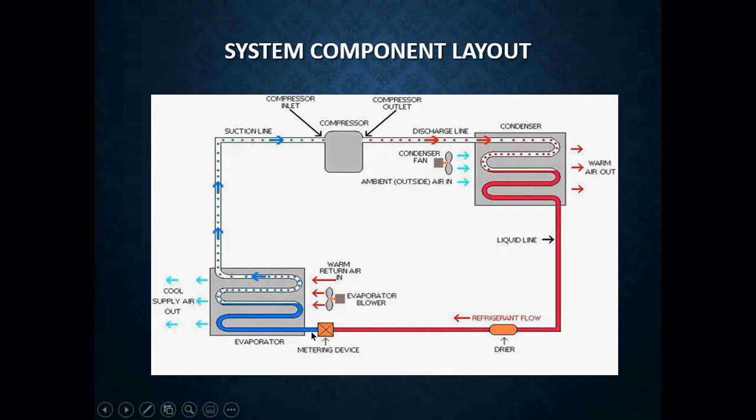And when I do that, I am able to allow the refrigerant to expand. And by doing so, I have a low pressure, low temperature, subcooled liquid enter into my evaporator, where my evaporator begins to absorb heat as air is passed through it. And when that happens, I begin to change state from that low pressure, low temperature subcooled liquid to a low pressure, low temperature superheated vapor.